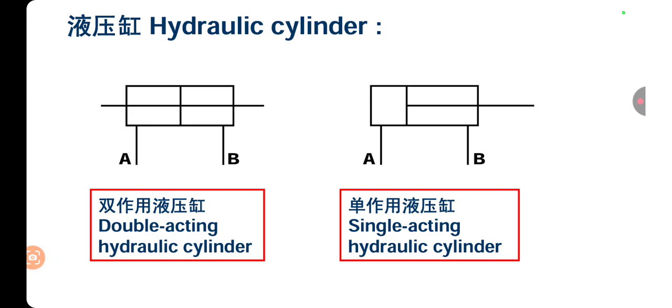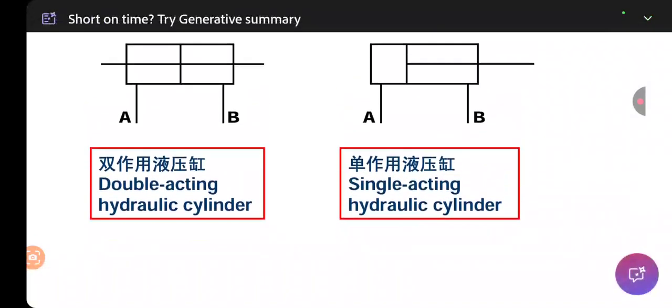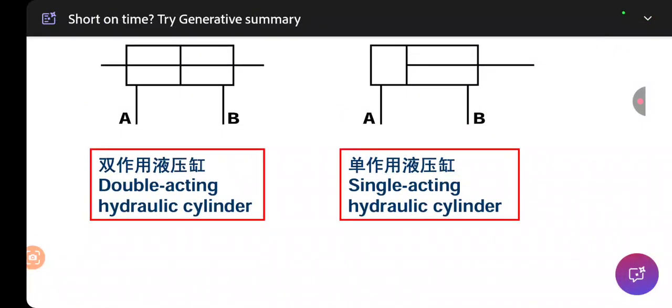But in the case of a single acting cylinder, it can be used in the press, or you can say the best example for the single acting cylinder is the bottle type hydraulic jack. It's single acting. It only allows the oil in one direction, and you have to put some force to release the pressure towards the tank with the help of the force you applied.